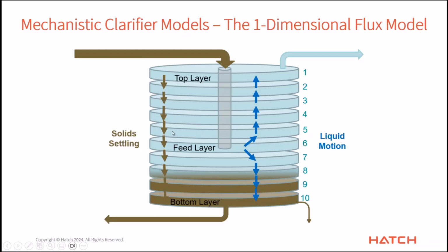And so as you'll see in the settling curve, we need a minimum amount of concentration for flocs to form. And then there's kind of like a peak sweet spot where they settle quite quickly as they're flocking together and falling down. In the high concentrations down here, they don't settle as quickly anymore, as it's now kind of into that layer of sludge and compression settling and compaction down there. Right. Okay.